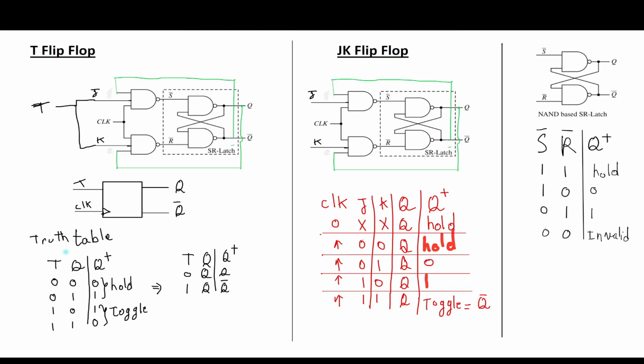Me personally, I don't like to memorize things. I like to actually understand how we derive this table. So in order to do this, let's do it row by row and refer back to our full circuit up here. So the first row, we have the toggle is 0. So let's get rid of J and K to eliminate the confusion. On the first row, again, the toggle is 0, so this will be 0 here.